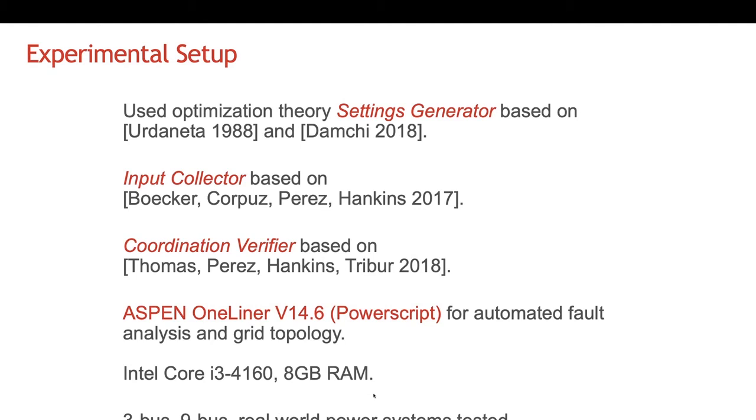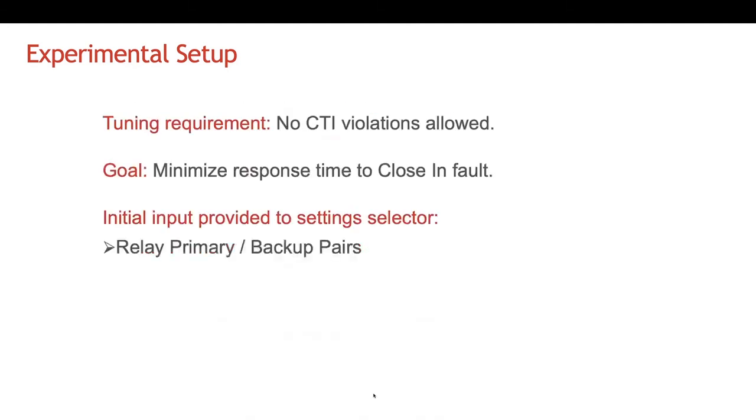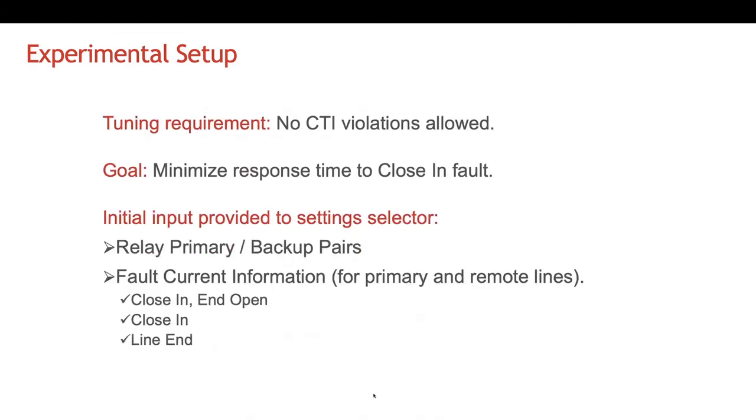We tested 3 real-world systems, 1 real-world system and 2, actually, they're the ASPEN sample cases. I'll show you the 9 bus here in a second. So our tuning requirement is TI restrictions, but respond to a close-in fault as quickly as possible.